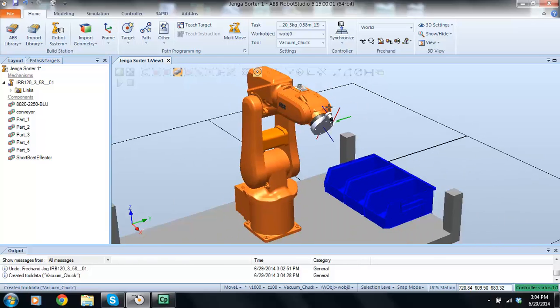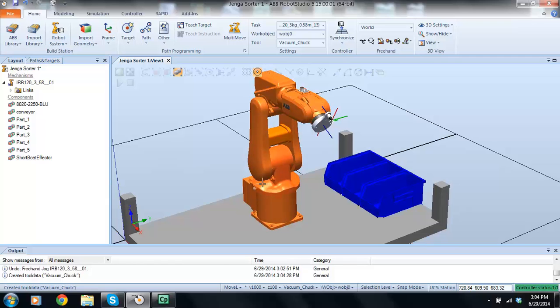The next thing we need to do is, this is just a robot that we imported. We've calibrated our industrial robot in the college, and we need to get that calibration data and import it into this controller, so they're both the same. So what would be the problem if we didn't do that? We've adjusted that robot slightly, we've done things to it. We need to ensure that this virtual controller has the same calibration data as the real robot. So how do you do that?